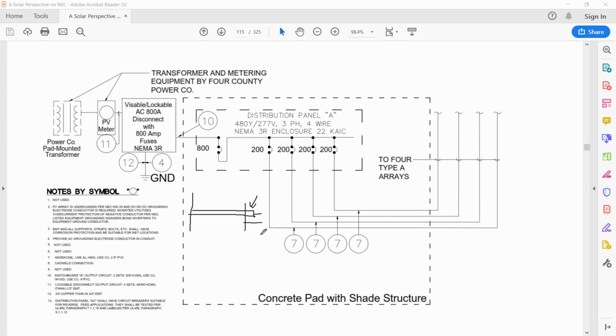And then I landed it on my terminals. I had 2 terminals here, and I was getting a fault between my 2 terminals where the cabling was stripped too long. And so you might come across different inverter systems with different terminal blocks, and for some 1/2 inch is just fine and dandy, and for others, stripping off a 1/2 inch is way too much.